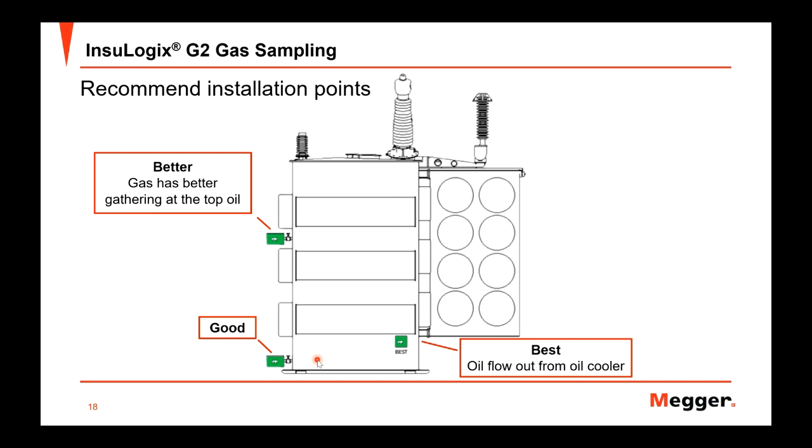This position can get the result too, but the result may be a little bit slower. It still can get there eventually because all of the gases inside your transformer will flow all over the transformer eventually, but the result will be a little bit slower than this point or even this point.